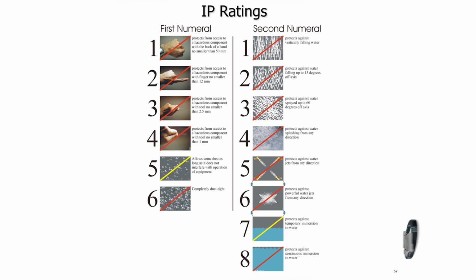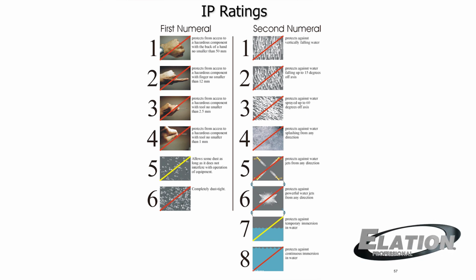Number 5 protects against water jets from any direction. Number 6 protects against powerful water jets from any direction. And number 7 protects against temporary immersion in water. And then number 8 protects against continuous immersion in water.